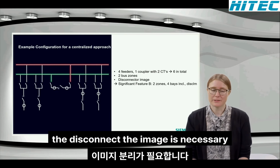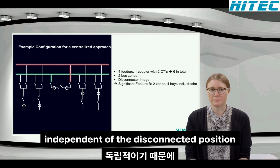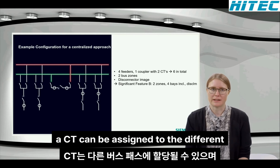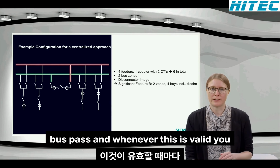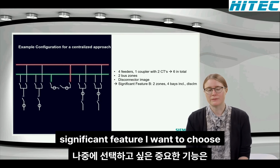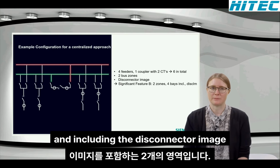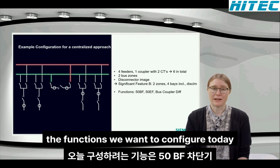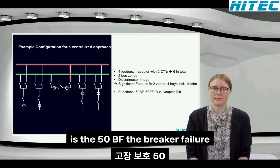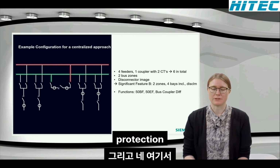The disconnector image is necessary because independent of the disconnector position, a CT can be assigned to the different busbars, and whenever this is valid, you need a disconnector image. So the significant feature I want to choose later is the 2 zones with 4 bays including the disconnector image. The functions we want to configure today are the 50BF, the breaker failure protection, 50EF, the end fault protection, and the bus coupler differential protection.